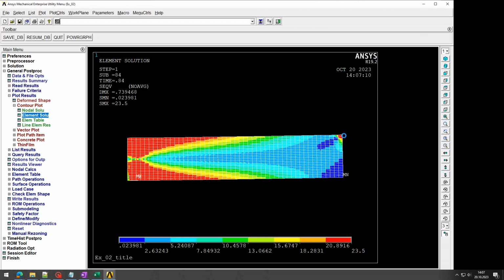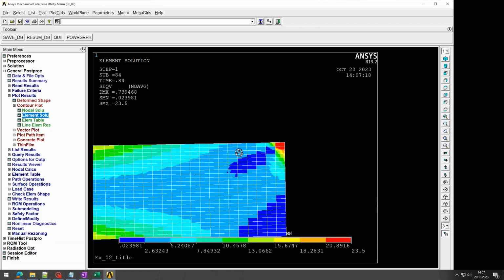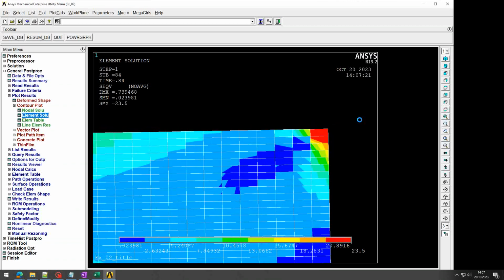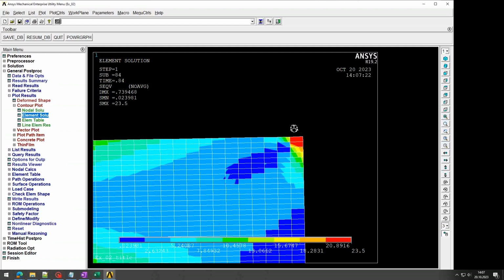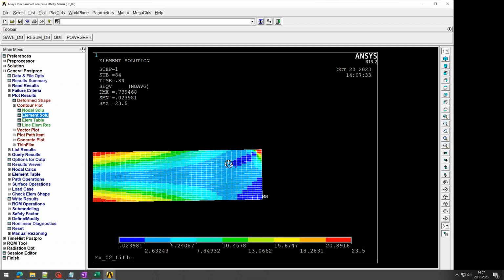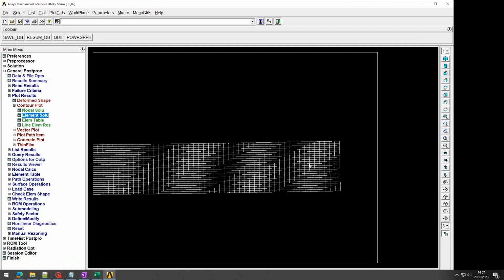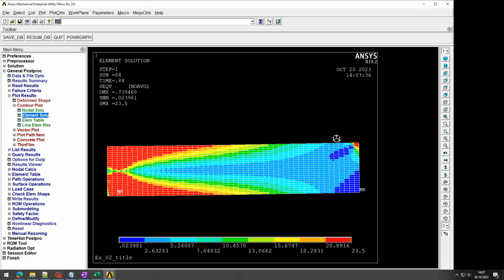And you see here, at least it was possible to see previously, that there is a distortion of the element. This happens because we have a very concentrated load. So also, depending on how you define the load in your model, that might generate some problems. So it's not so easy to say which is the right solution. It requires further study.